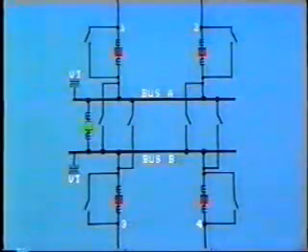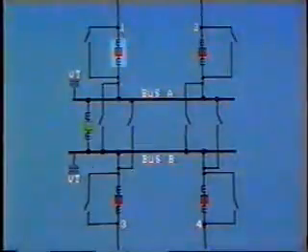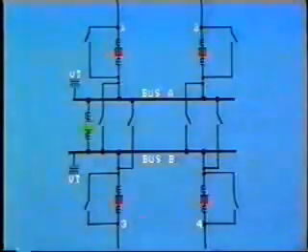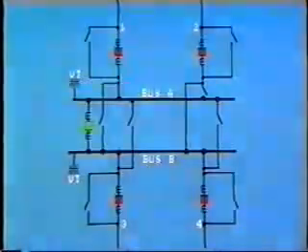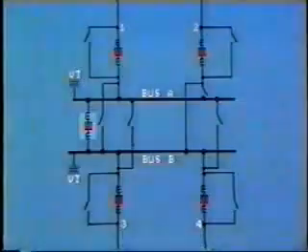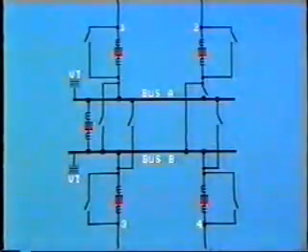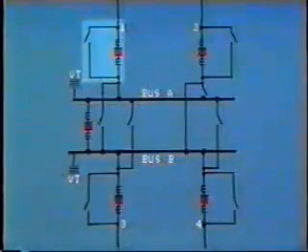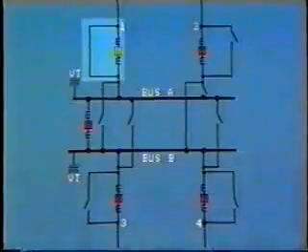In order to provide more flexibility, this configuration allows us to remove a breaker from service without interruption. For example, let's say we wish to remove breaker number 1 on circuit 1. All of the remaining circuits would now be connected to the B bus. The bus tie breaker would now connect bus B to bus A, which now becomes the transfer bus. The bypass disconnect on breaker 1 would now be closed. The breaker is opened and disconnects opened so as to isolate the breaker for maintenance.